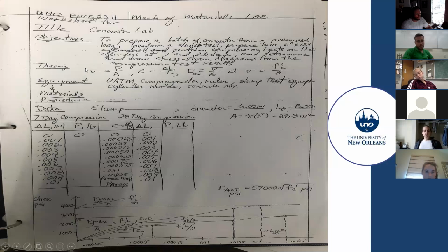First equation is the same as we have seen on the tensile. Sigma is the stress, and it can be calculated by dividing the load, applied load, by the cross-sectional area. And I explained how to calculate the cross-sectional area. I showed the cylinder 6x12, and the cross-section, if I cut the cylinder in half, I can see what the diameter is, and I can calculate the cross-sectional area. This way, I can calculate the intensity of the applied force.